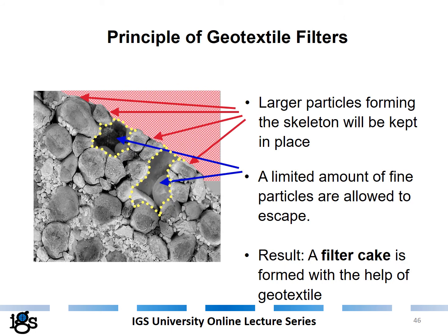I want to explain briefly the principle of geotextile filters because especially experienced engineers are very skeptical on how such a thin layer of geotextile can provide the filter function because they know granular filters have to have a certain thickness. So when we place a geotextile filter here, what it does is keeping the larger particles in place, forming the skeleton,